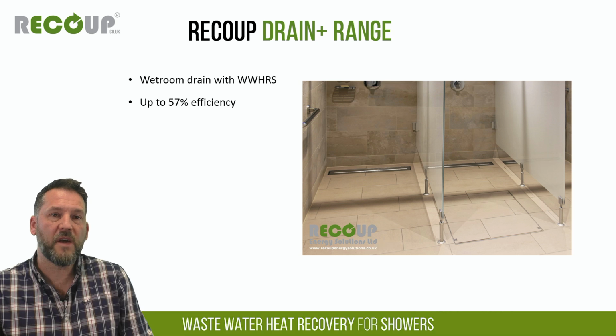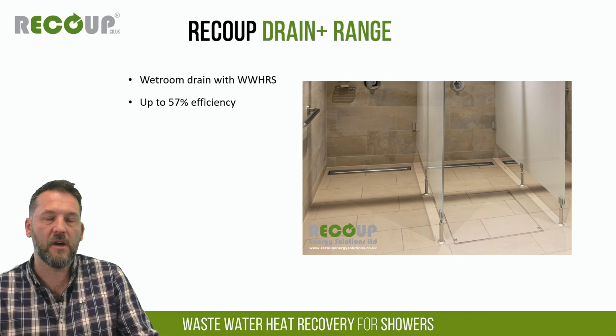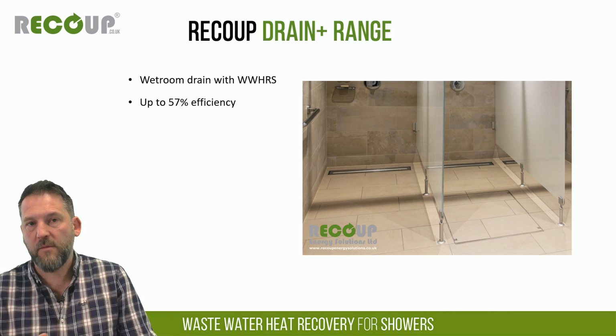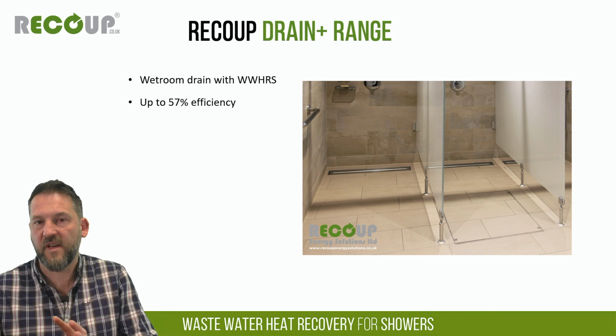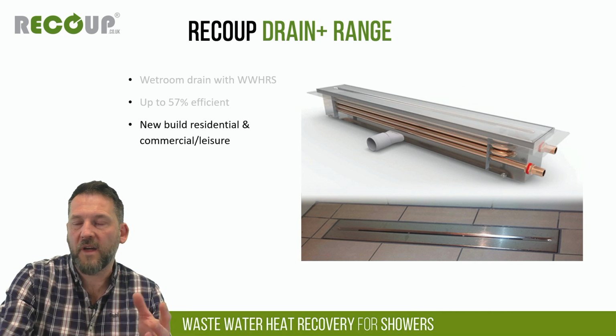Just to complete the picture, not really used too often in residential, but we do have a range of wastewater heat recovery integrated wet room drain channels. These are linear wet room drain channels that would normally be recessed into a tiled wet room floor or a vinyl wet room floor. Anywhere between 35 and 57% efficiency, depending on the product. But these work in a similar way.